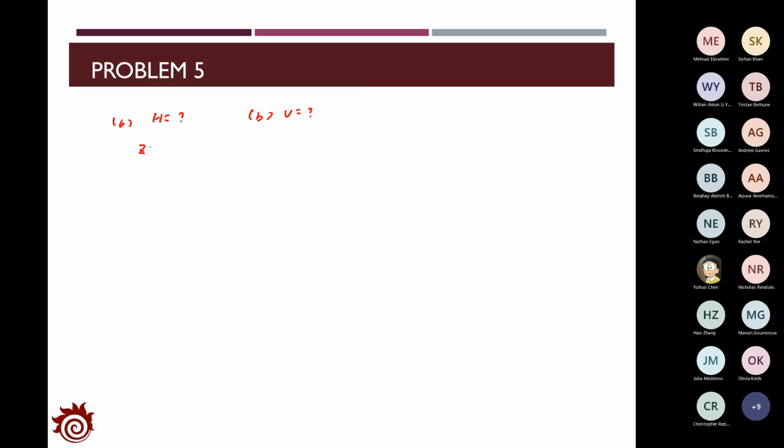And for the horizontal distance, that's problem A, and vertical distance. Here you are provided with the zenith angle, which is 86 degrees, 32 minutes, and 42 seconds. With that you can find out the vertical angle theta, that will be 90 degrees minus the zenith angle, which gives the result as 3 degrees, 27 minutes, and 18 seconds.